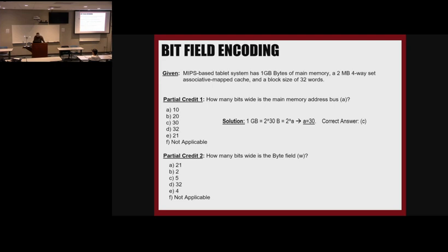That's a good question. Let's say we have real tablets, and one of them has 1 gigabyte of main memory and another one has 4 gigabytes of main memory. Do we, as designers, really change the size of the address bus because of the size of the main memory? Today, no. If I'm AMD, I wouldn't do it, because you have already designed instructions and architecture for 32 bits. You just don't use some of the bits.